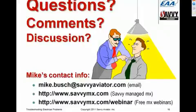Well, that's not going to be a battery problem for sure. If the voltage drops to 25.4, it basically means that the alternator has stopped supplying power, and the aircraft's running on battery power. So whatever is wrong with his airplane is not a battery problem, it's a charging system problem.